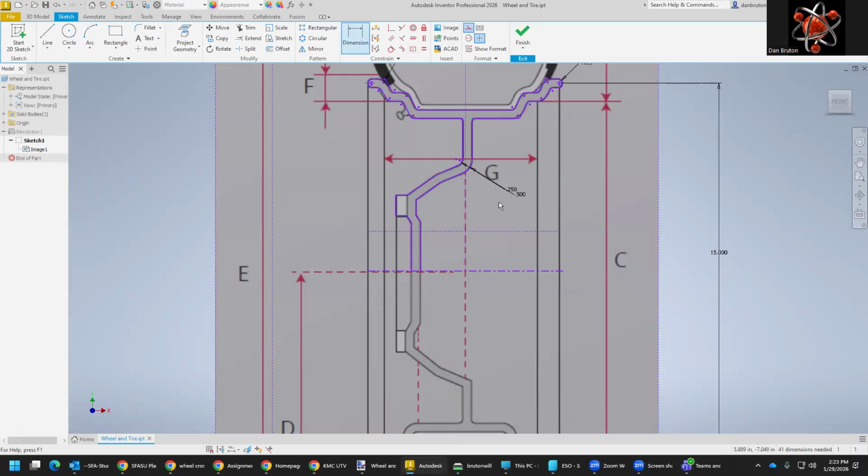So what we'll do here is we'll say dimension, we'll go here and we'll type in 156 mm, even though we are in inches. Now, this means that this box needs to be centered up there. So what we're going to do is delete this one. Oops. Delete this one, this one, this one. This is where our hole is going to be for the hub.